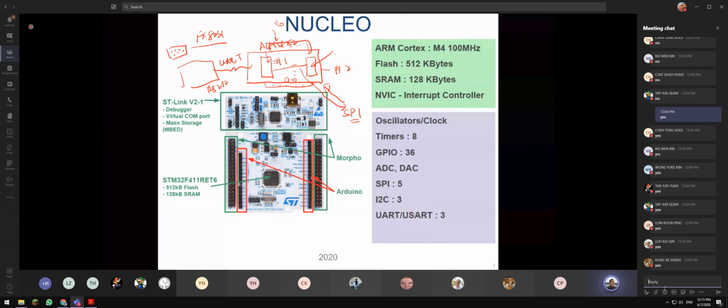My target firmware is loaded into microcontroller 2. Students can download the code into microcontroller 1. Basically, microcontroller 2 takes all the hex code that is downloaded, does the processing, and sends all this hex code into the target microcontroller 1. I hope you got what I mean. At that time, I developed this using Delphi, because in those days Delphi was faster than C programming. I'm not sure why Delphi is no longer popular in the market. You can have a look at Delphi programming.